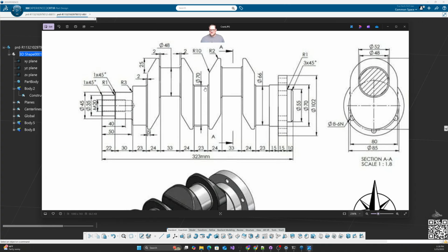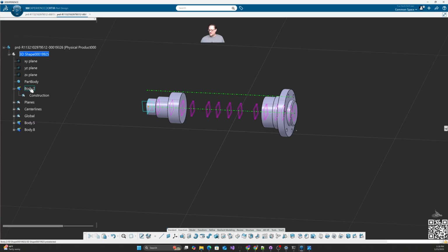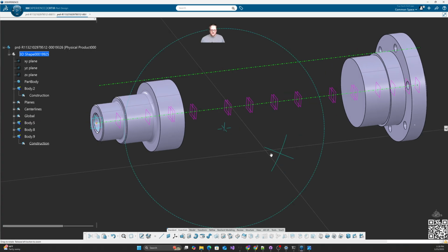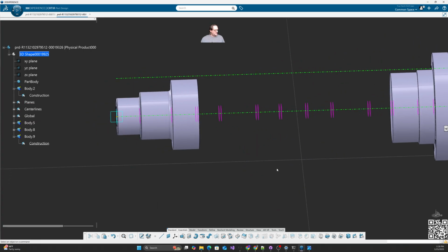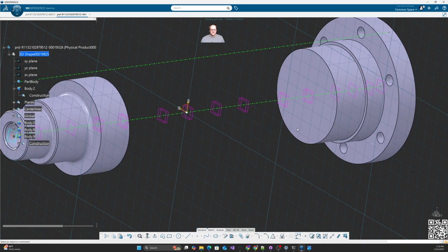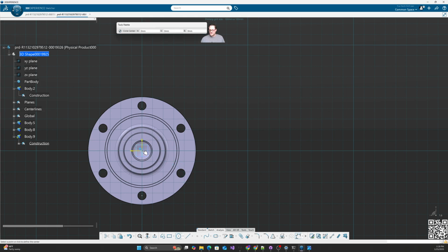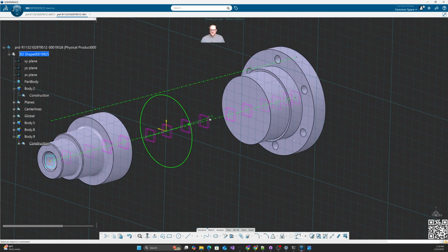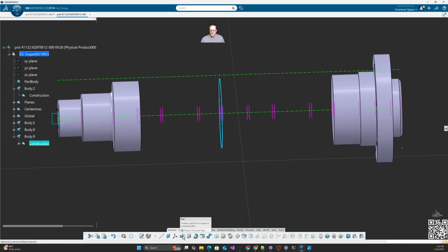So in order to do that, this is diameter 70 here. So let's do that real quick. So again, we'll copy and paste our body, define a work object on our construction. We know it's in this center region right here. So we'll do a sketch on this plane, making sure we're curve intersection. We'll draw our circle, 70. Oh, sorry, I said 66. Exit the sketch.